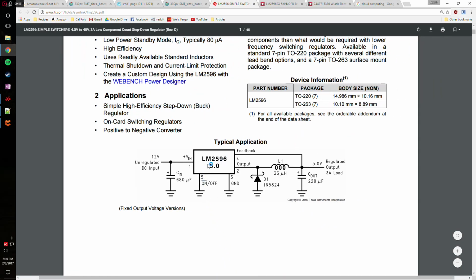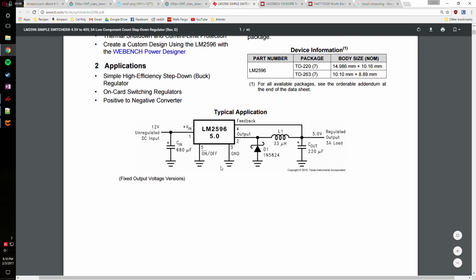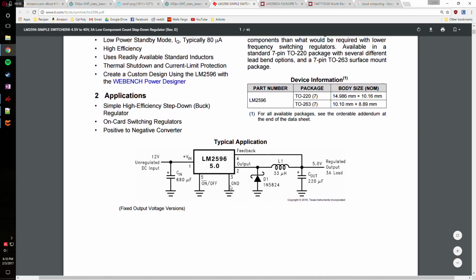This is a buck converter, and it's basically displaying which pins of the buck converter are connected to which types of components. And it's kind of just like an overview of what is connected to what. So an engineer looks at this and sees, the input's connected to pin 1, the output's connected to pin 2, you've got some inductors and capacitors, many of which are connected to ground, and all the connections in this circuit are connected in such and such a way.